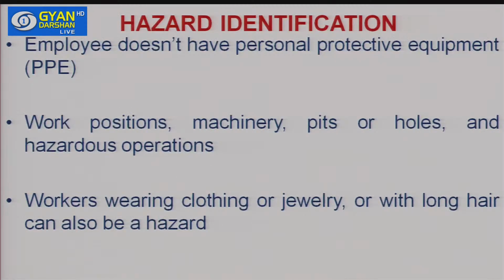Then workers wearing loose clothing or jewelry, or with long hair, can also be a hazard, because the hair can get stuck somewhere in the machinery, or the long clothing can get stuck, and then the moving machinery can pull you inside the machinery. So it's a very dangerous situation.